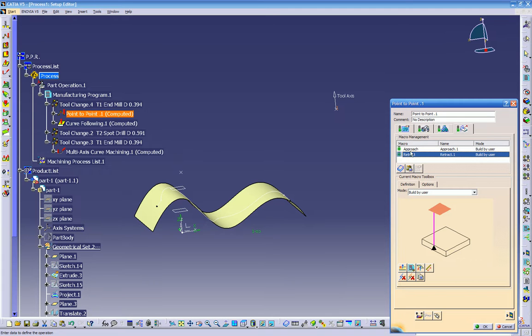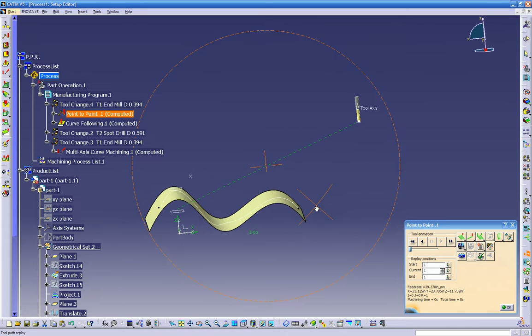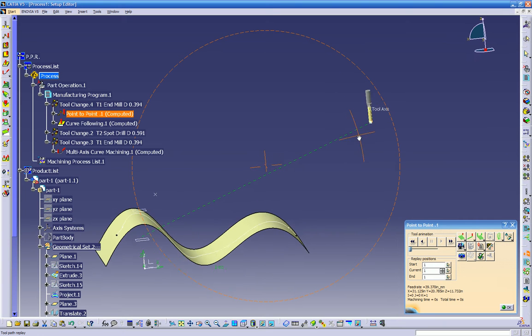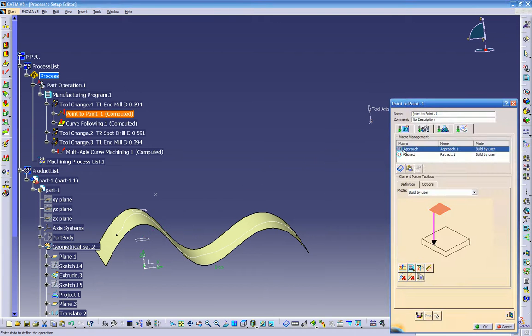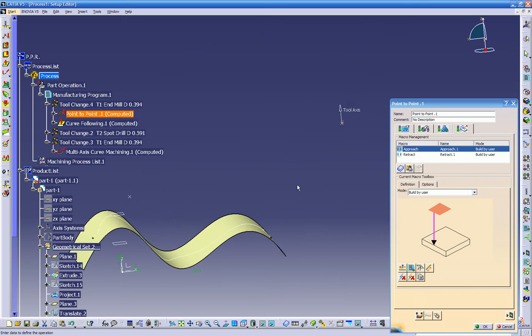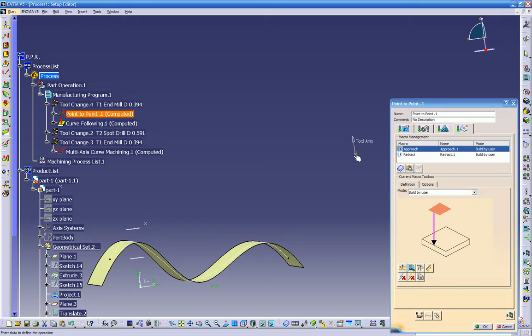Let's see what option we have in here. So I'm gonna deactivate this. Click on here, deactivate, and let's do a toolpath replay. There we go. So as you see right now, our point is gonna bring the tool right into that point that we created. The reason it's coming down is because we have this plane here activated. Approach. I was trying to go to this thing, but you can put your retracting approach however you decided. So we cannot use this option right now because it's going to ask us to choose a plane, and if you look at the plane, it's way below this point.